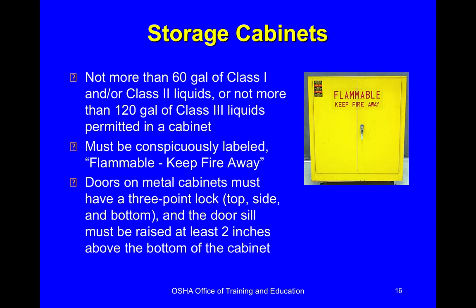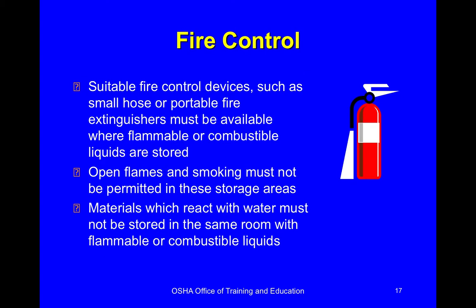Flammable safety cabinets or storage cabinets. These are insulated. They must be grounded. And also, if there are going to be fumes inside, they have to be vented to the outside. We'll look at these more this summer.